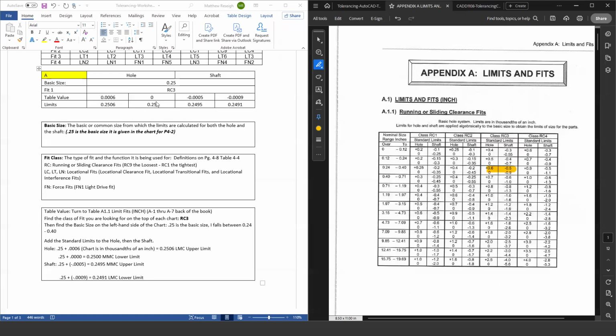So that might look like, if I was dimensioning that on a drawing, I would have modeled my part to probably be 0.25, so that when I dimensioned it, there's my basic size showing up, 0.25. And then I would have built a dimension style that says plus 0.0006 minus 0 would be what my dimension style might look like.